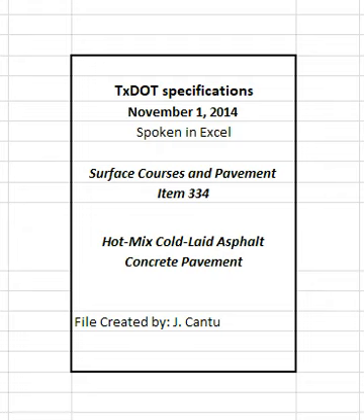3. Equipment. Provide required or necessary equipment in accordance with Item 320, Equipment for Asphalt Concrete Pavement. 4. Construction. Design, produce, store, transport, place, and compact the specified paving mixture in accordance with the requirements of this item. Provide the mix design unless otherwise shown on the plans. The department will perform quality assurance, QA, testing. Provide quality control, QC, testing as needed to meet the requirements of this item.